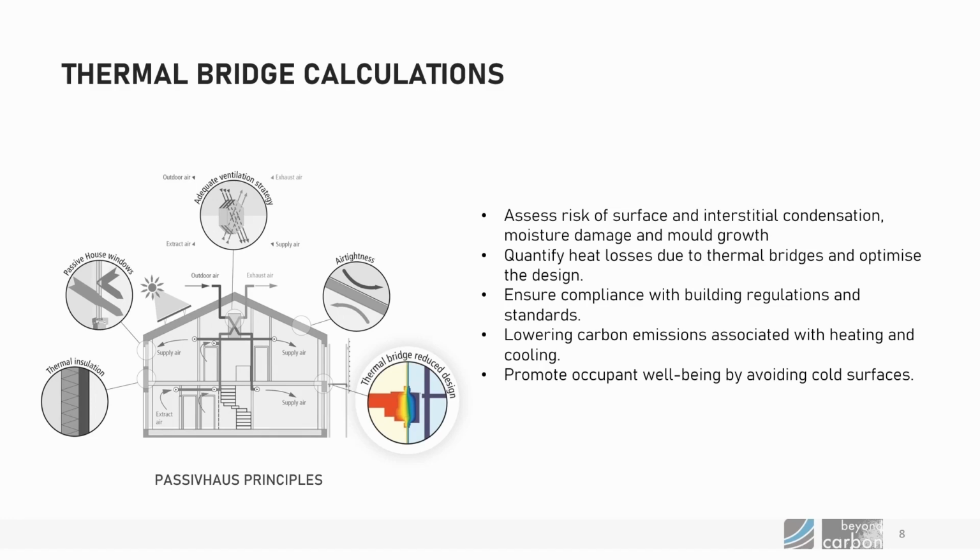And if we design out thermal bridges, we can reduce building carbon emissions associated with heating and cooling. And we can also promote occupant well-being by avoiding cold surfaces. Any surface in a building which is significantly lower than the ambient temperature can produce discomfort.